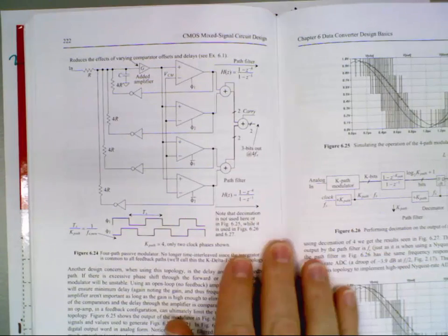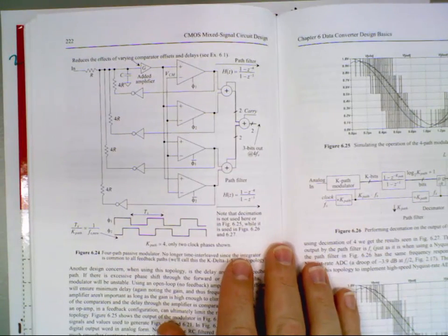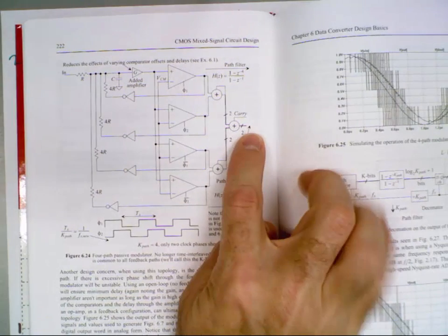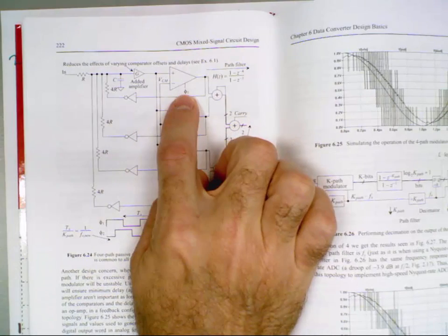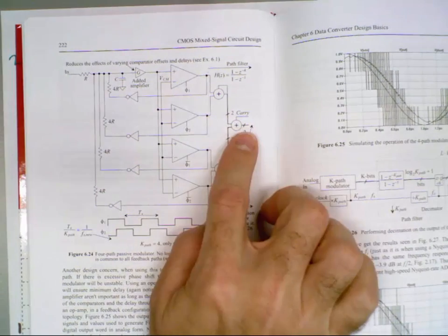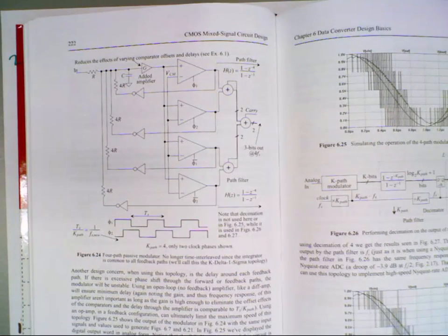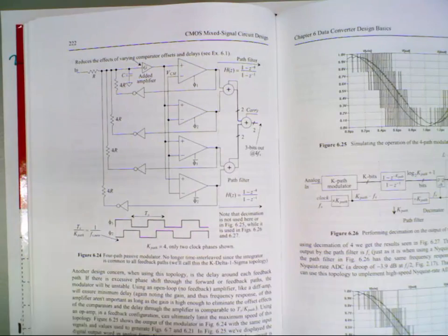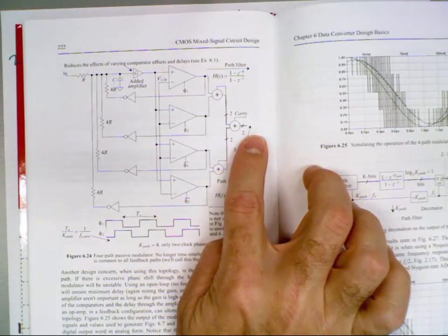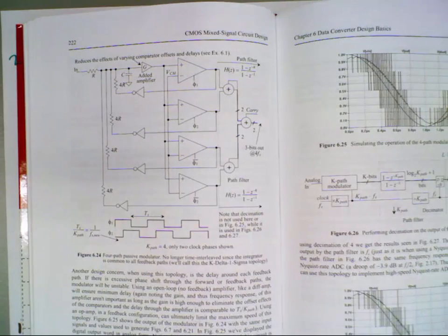Now, when you go through these sims, so basically this is adding all the bits together, and they're coming out at a rate which is the clock frequency, the slow clock, say 100 megahertz times 4. So the bits are changing at 400 megahertz coming out. But you still have to look at, when you add all those together to get a 2-bit word out, you still have to look at them as that is an averaging filter.